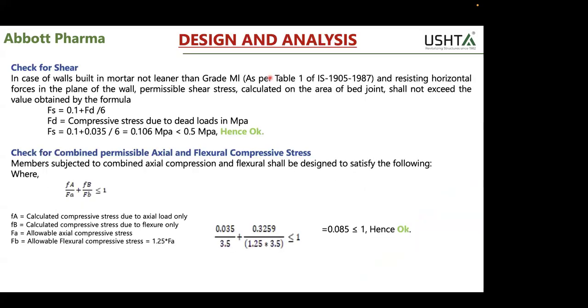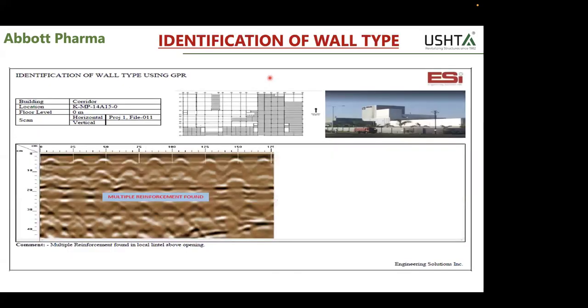So what was happening here was that some of the infill walls were failing during earthquake, so they wanted to stabilize that. Earlier the structure was passing, but when we transferred that force to the wall, I mean when we were strengthening these walls, some of the members would also fail. So how would we avoid that? We used a technique of energy dissipation. I'll show you what we did.